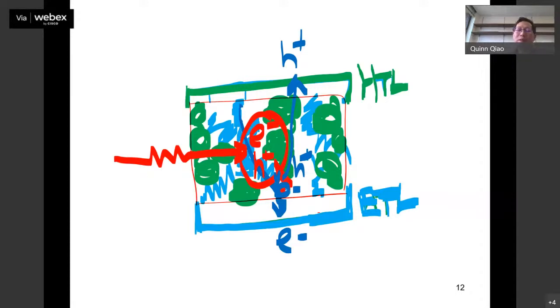So typically in organic solar cells, you want to form a network, right? There should be a continuous pathway like this for electrons, and then like this for holes. All the green should be connected with each other to form a good network. All the blue should form a good network for itself. When the excitation is generated either in the N-type or P-type, the donor or acceptor, it will reach the interface, get dissociated, and then the electron finds its own network to go. The hole finds its separate network for transport. That's why the hole is collected on the top and the electron on the bottom. This depends on whether you have an inverted structure or conventional structure. Does that answer your question?